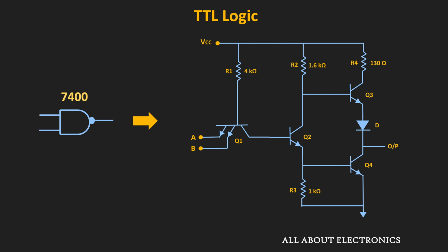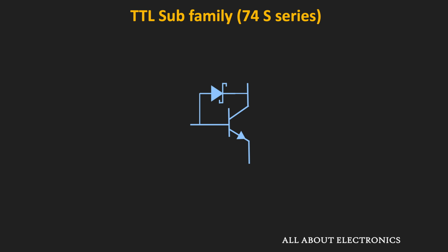So if you see the Schottky transistors, then they use a Schottky barrier diode between the base and the collector of the transistor. So this arrangement does not allow the transistor to go into saturation. And in this way, that eliminates the problem of the excess charge stored in the base of the transistor. So here, when a sufficient amount of base current starts flowing through the transistor, then the transistor starts going into saturation. And due to that, this voltage Vc starts reducing.